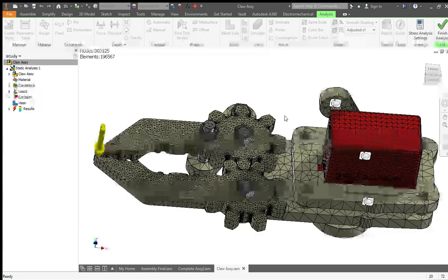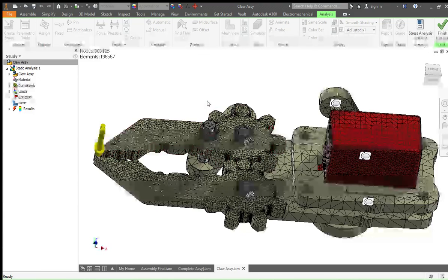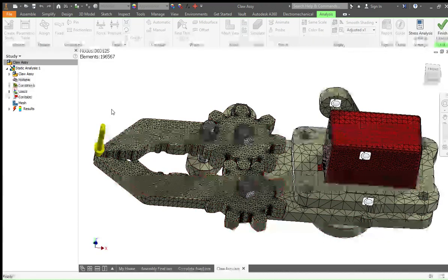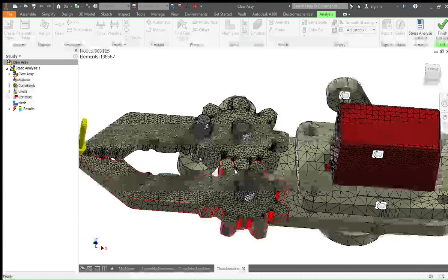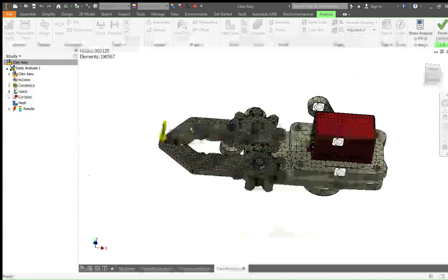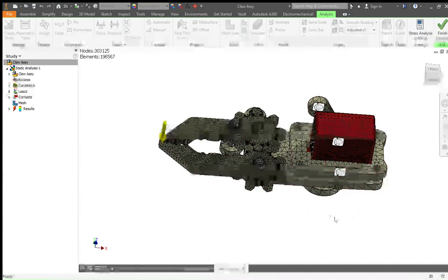While it's doing that, I'll maybe just talk about a few of the options you have with your finished guide. It's often not obvious with any FEA, especially when you're looking at something like the von Mises stress, where the high points of stress are, because there'll be one. Oh, here we are, a good example. There'll be a few points where it's really extreme, but let's just change this back to the default settings.